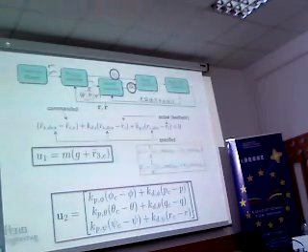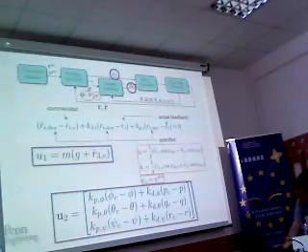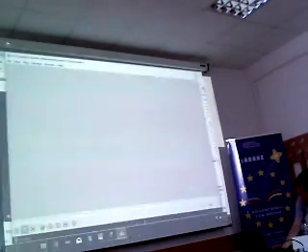We do that using the linearized equations. If I know what the commanded acceleration needs to be in the x and y direction, I can calculate the roll and pitch angles and their derivatives. And similarly, I can determine the commanded yaw angle. So we will go back a little bit in order to understand this formula. Okay.